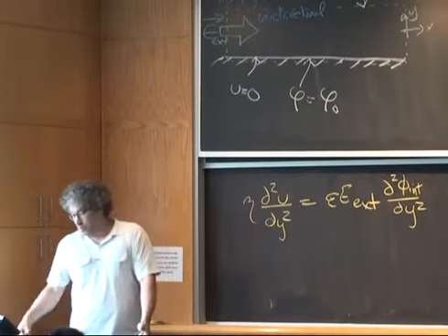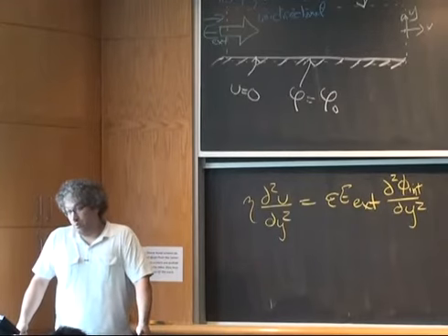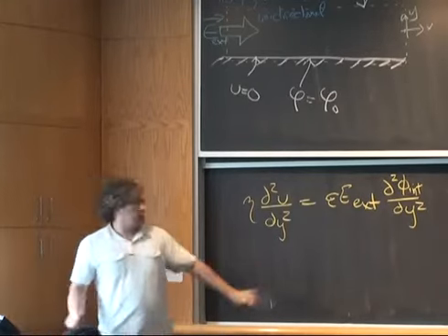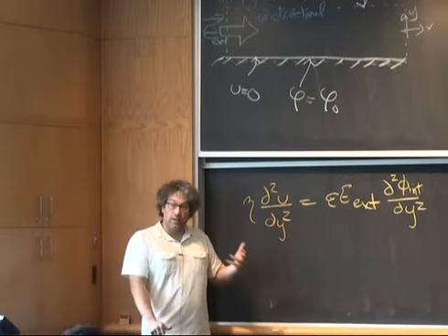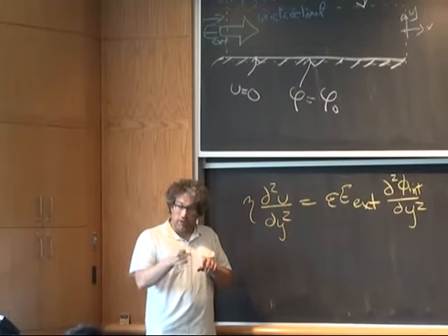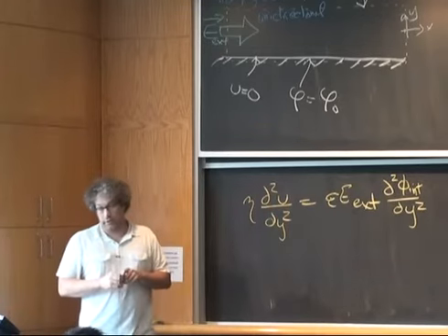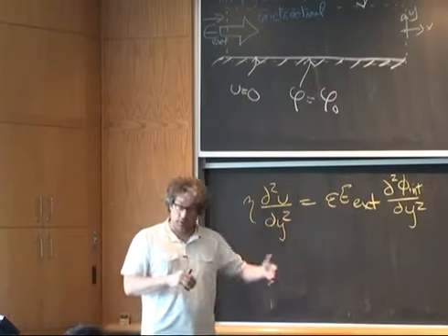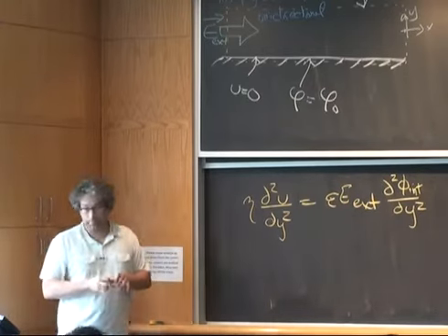You'll find that those phenomena tend to dominate primarily when you use AC forcing. If you use a DC field, you see that all the linear stuff dominates. If you use AC forcing, then the nonlinear stuff dominates. And the creation and then actuation of a space charge is inherently nonlinear, because the space charge you make is proportional to the electric field, and then the actuation is also proportional to the electric field.